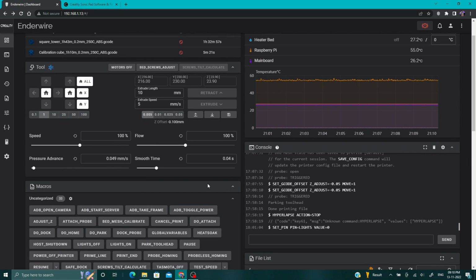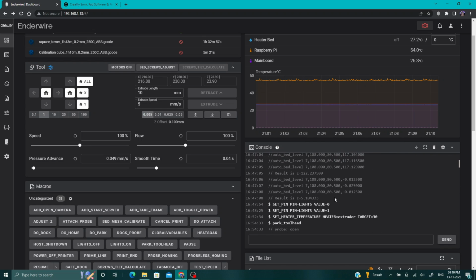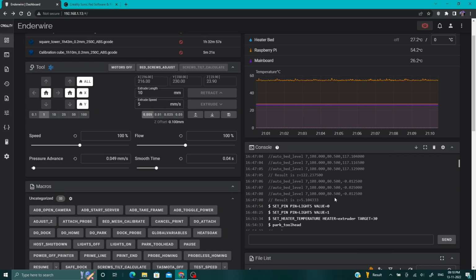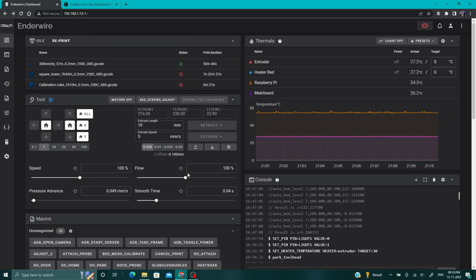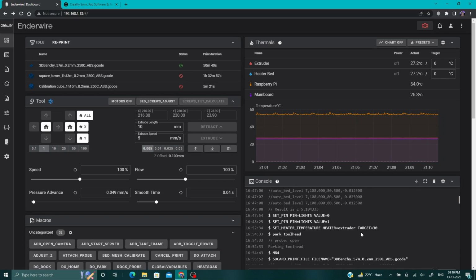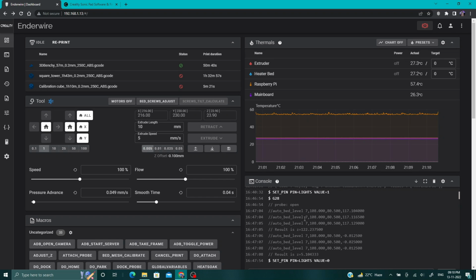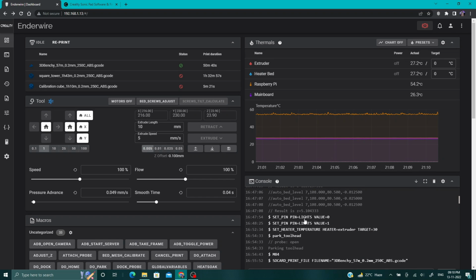And you remember the Z offset, right? If I go a little bit up, when my clicky probe is doing its Z limit calculation, it probes three times. So as you can see here, the result is 5.104, but the set value of Z offset is 4.9 in the printer.cfg.